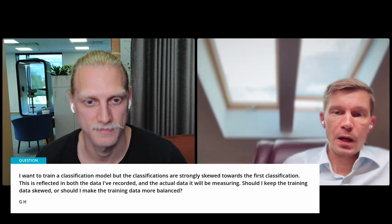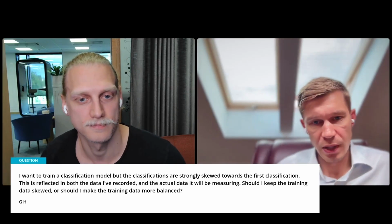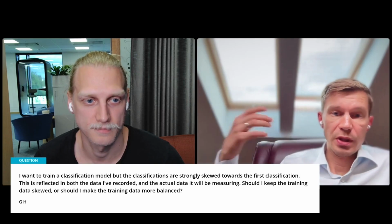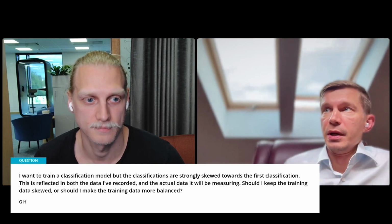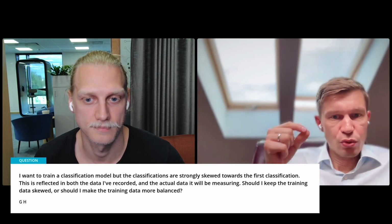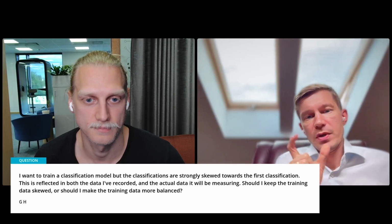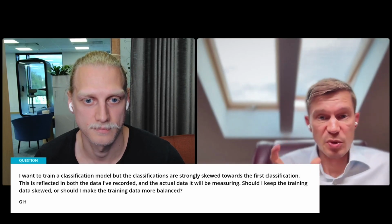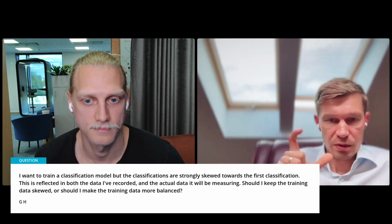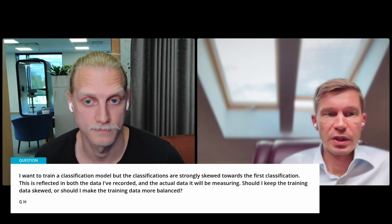In your C code, you would then treat certain probabilities as certain classes. For example, you will raise the threshold for predicting the minority class. And also, in addition to that, you would introduce a step to maybe have two consecutive predictions of this class because your window moves at a very small step, for example, like 10 times per second. And then you would need the model, based on your experiments, to predict this class twice with this threshold. And that would increase the confidence in predicting that class.